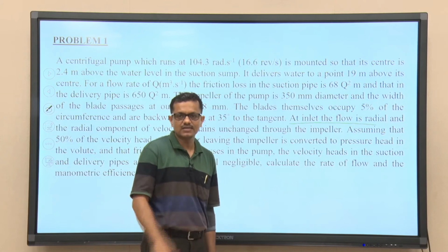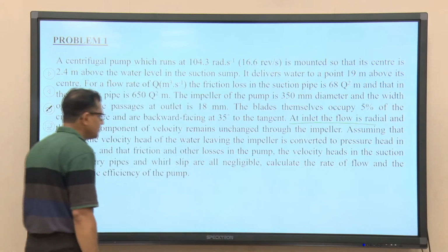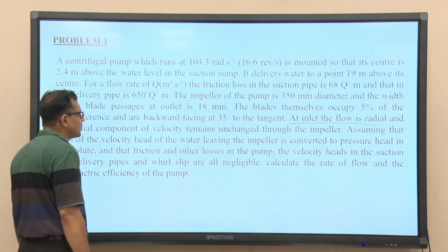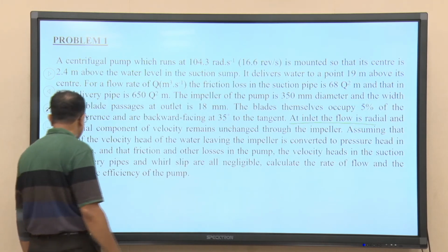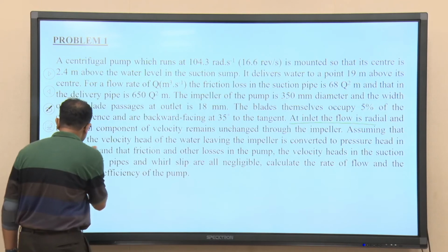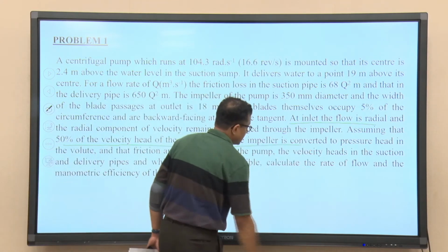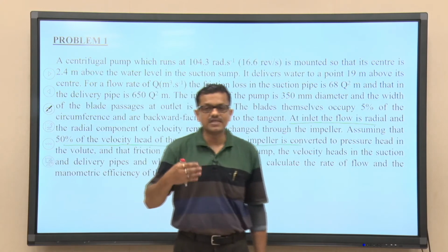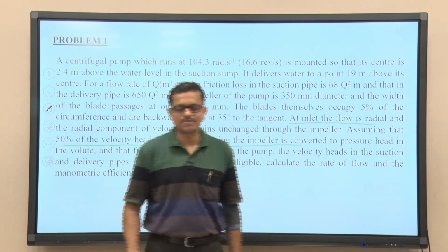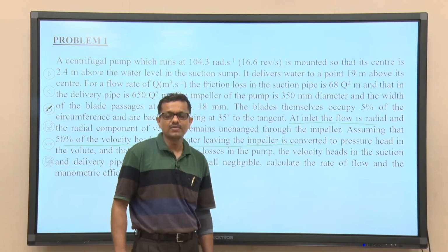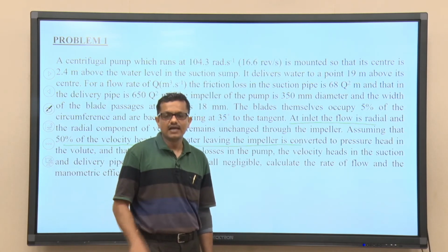We will be discussing that part again. Assuming that 50% of the velocity head of the water leaving the impeller is converted to the pressure head in the volute. That is again an important statement we need to understand clearly. I have discussed this part many times, that the objective of having a pump is to develop head.